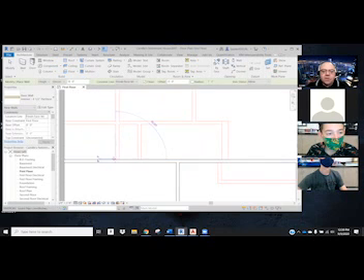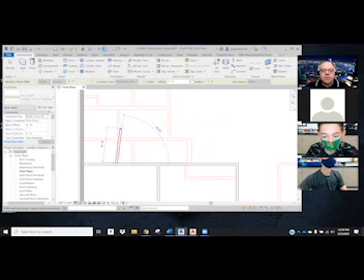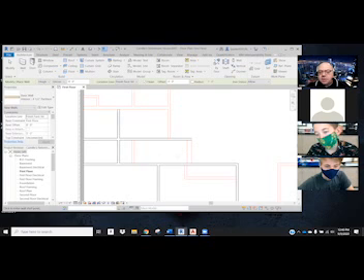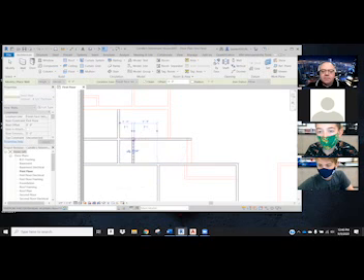And if I can find one and I can take it all the way through, space bar to flip them over if needed. And we're just going to do interior walls. So just keep drawing interior walls until you have them all done. Now, so you know, I'm going to leave this wall here as well. This is an opening. It's got some columns in it. I'm not sure what I want to do with that yet, so I'm going to leave that alone. But right now, I'm just going to do the walls as fast as I can.